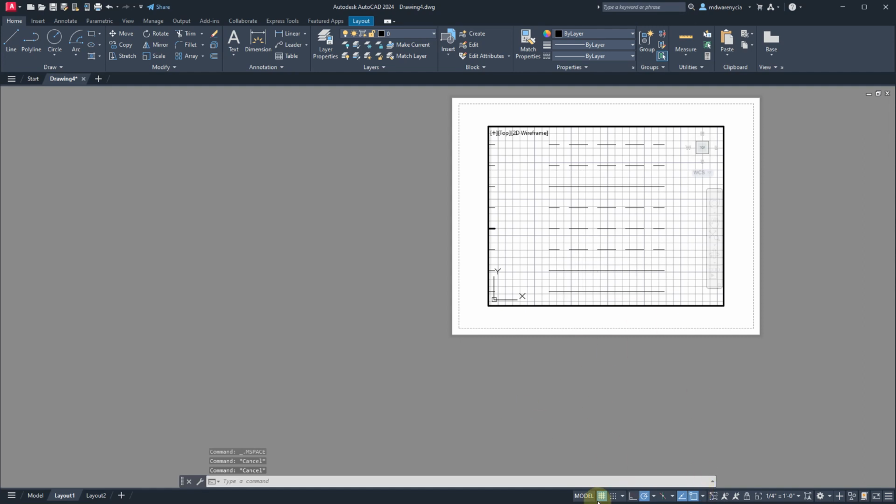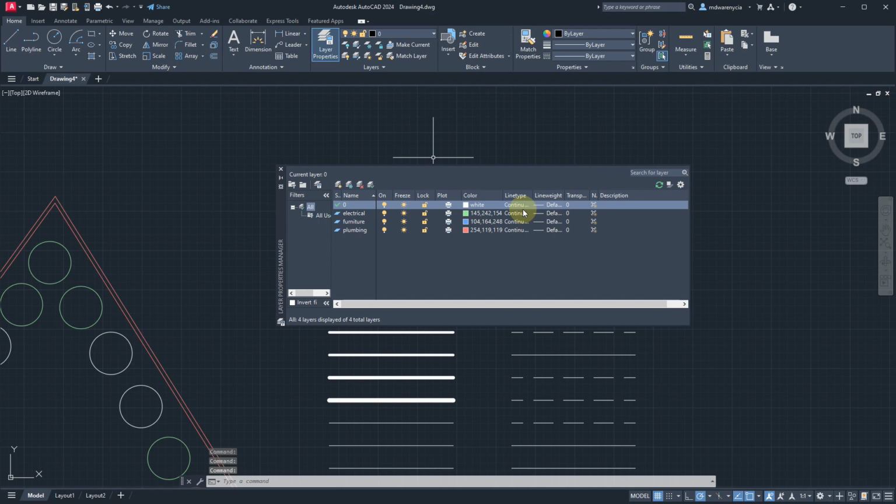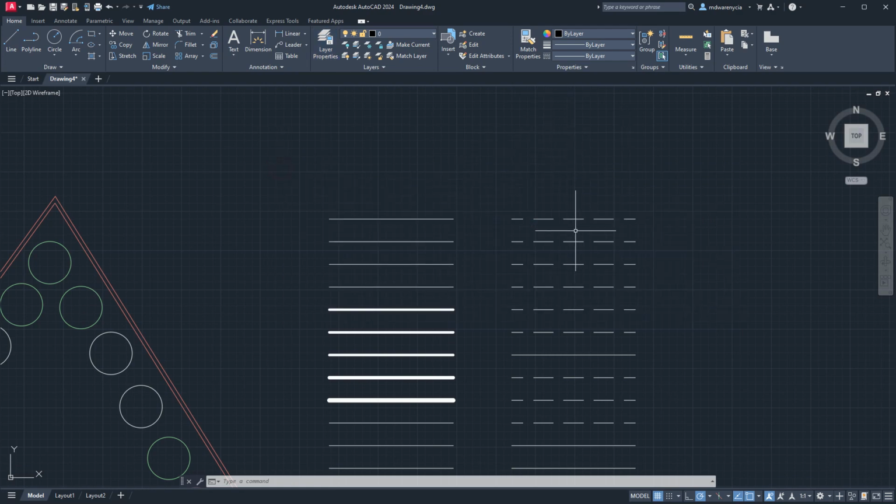Excuse me. You can get out of that viewport. So when we're talking about line weights, line thicknesses, all these configurations, remember, you want to try and set these settings here first. So you should ideally have your layer configured for the thing that it's doing. And then from there you would set your line type, set your line weight. Then once you're done, if you have any exceptions and you don't want to have an entire other layer for just one or two or three lines, then you would select those individual lines and then change them individually based on that. Okay.